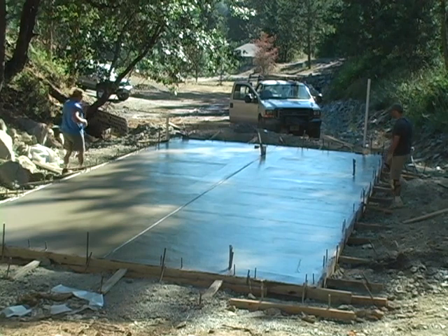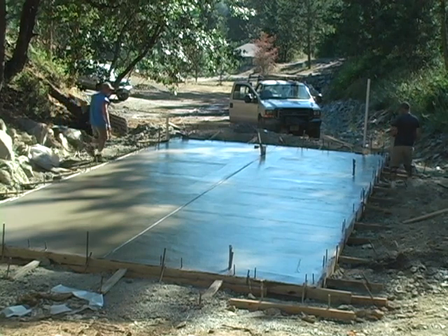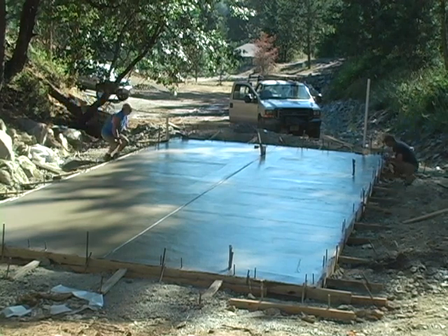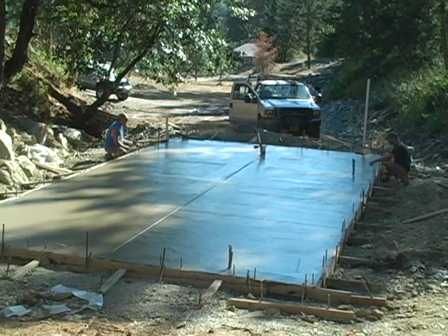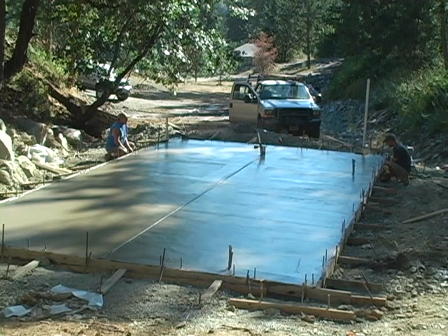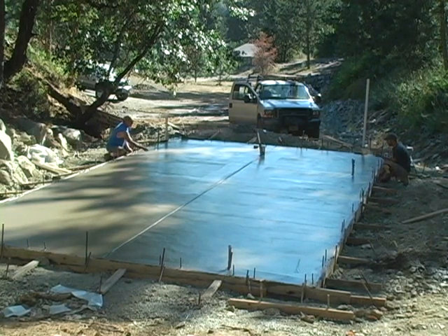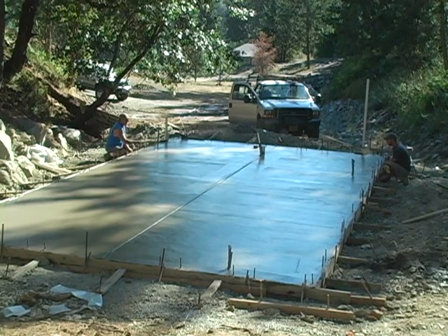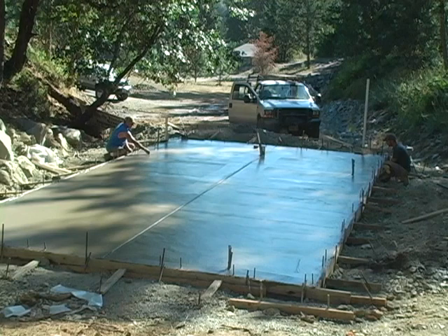Anytime you have a groove that's right on a wall, if that wall is framed slightly out of square, you're going to see it. It's going to be very obvious. Whereas if that groove is either buried in the wall or out 6 inches from the wall, you won't be able to see the variations in the framing at all. So here we just take a basic chalk line, put it on our marks, pull it tight, and snap a line, and then we can use our grooving tool right along those lines.